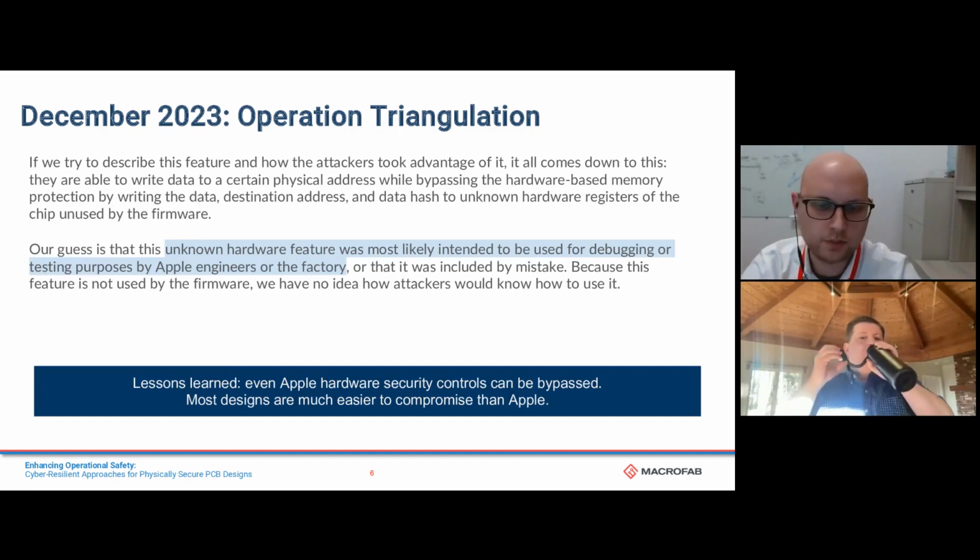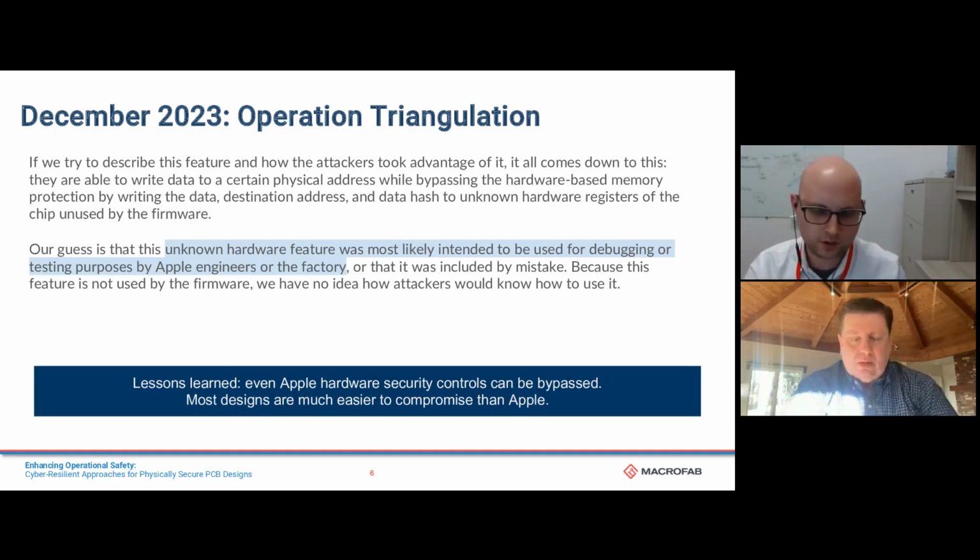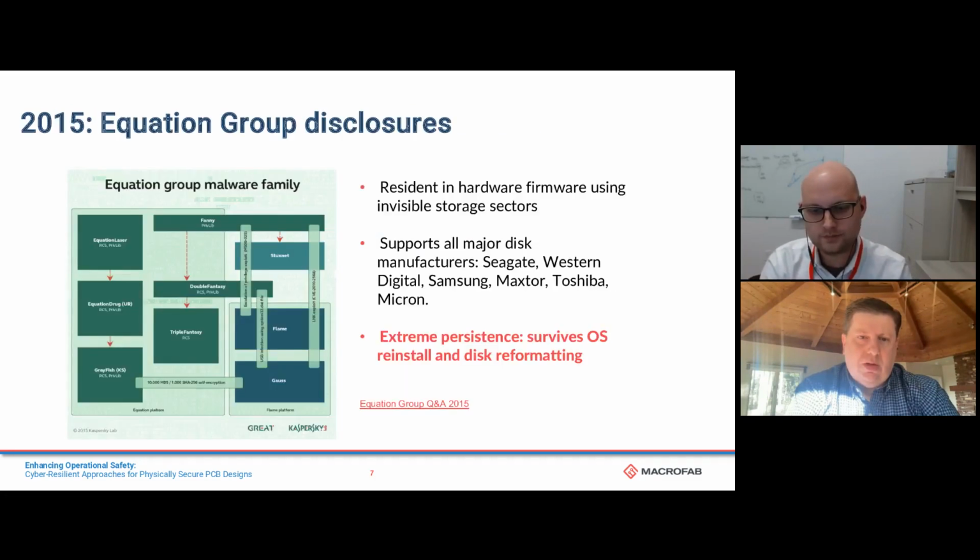As we'll talk about later too, this is a good example of how, at early stages in development, it's very easy to leave all of these great hooks into both your hardware and your firmware to make it easier to debug. There is a critical step there of legacy code being left in, or not enforcing your validation and test stages, if you're running a CI/CD process, to enforce that those things are turned off or removed or compiled out as opposed to getting left in. So this is a thing we'll talk about later as well.